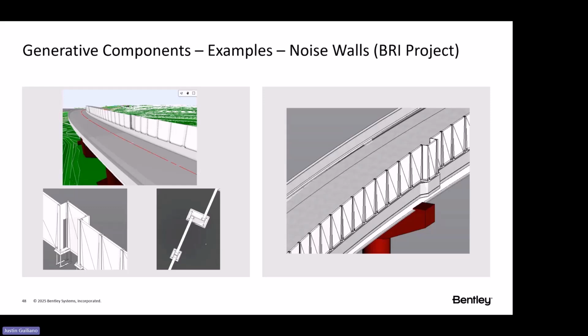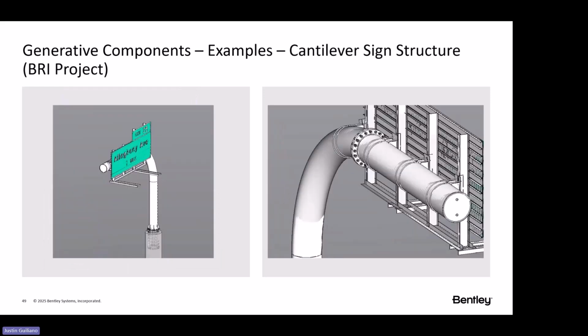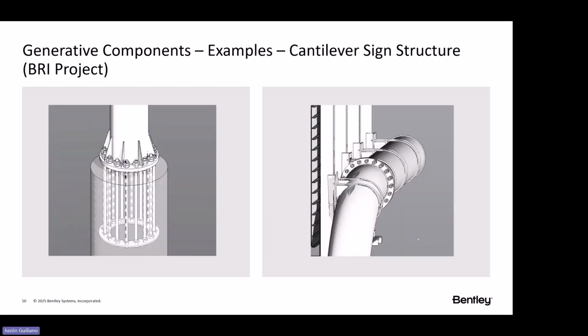Then basically we just did a linear pattern, or linear array, of saying, every X feet place this type of post. And then we used Excel to control the ranges. And then from that, we specified whether it was a type 1, type 2, what have you, and basically built all that stuff there. Here's a sign structure, a little more detailed one that we did for the Betsy Ross project as well. Again, that's got all of the assemblies on it, the U-bolts. We got the individual bolts in there, the end caps, the WT, W sections, the extrusions. So all of it. It can get really detailed really quickly. So there's a couple more screenshots. We got the anchors in there as well.